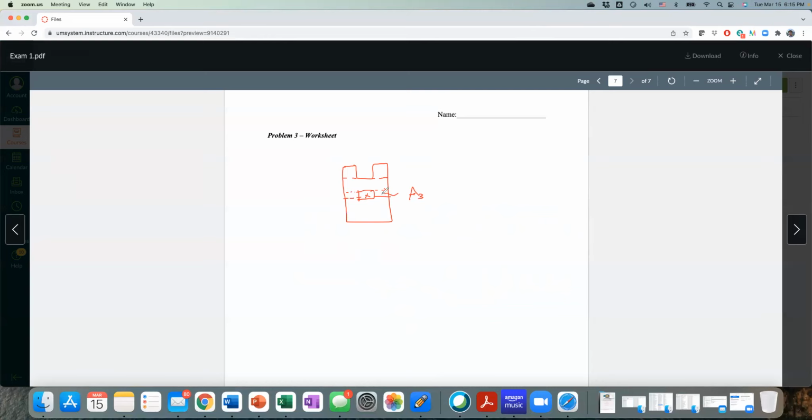So when we do the y-bar, you're using AC, right? AC is the total compressive area, so that equals A1 plus A2 plus A3, right? A1, A2, you already know, you calculate that out. And by separation, A2 is before you do the cutout.